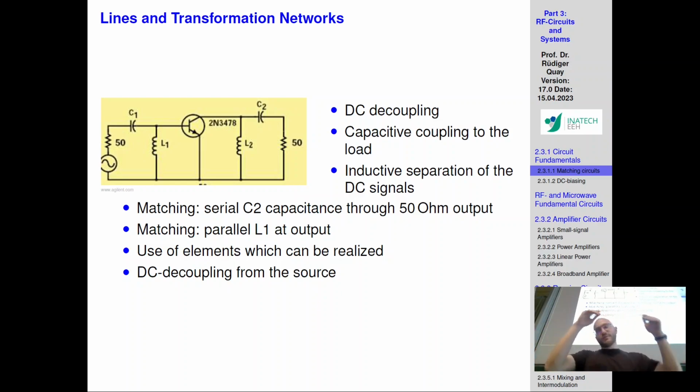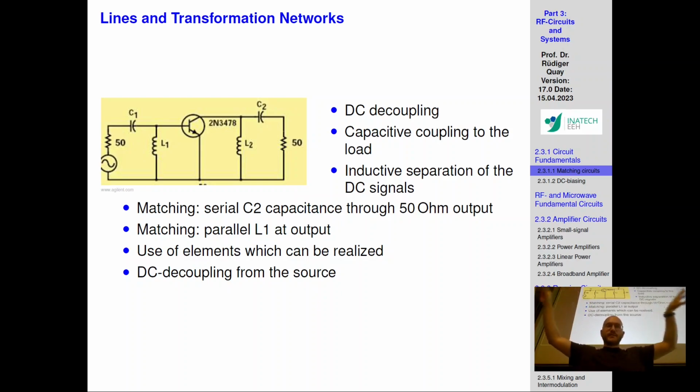Go back to the lecture video recording and you'll see it there. In principle, what you have is a series of RLC networks, or a series of LC networks. The R comes through the fact that you're doing microstrip line and coplanar line. You always have a resistance. You have a certain input-output capacitance and an inductance that comes through it.